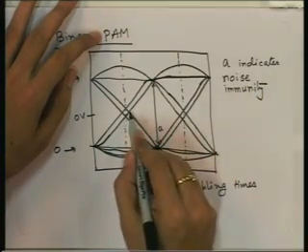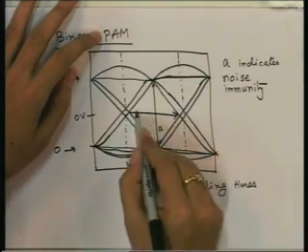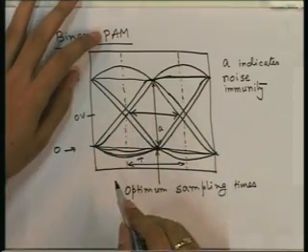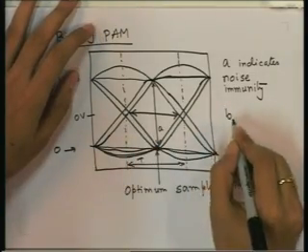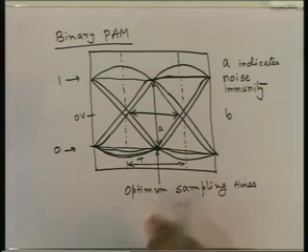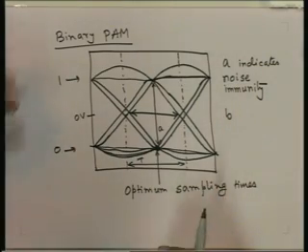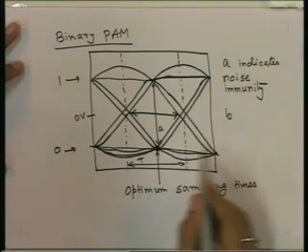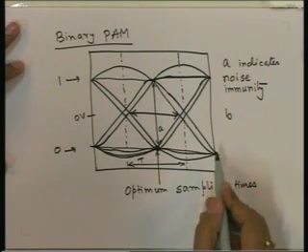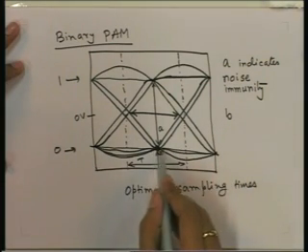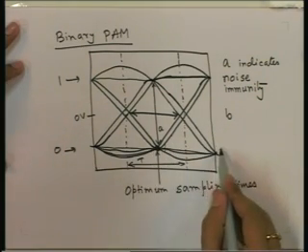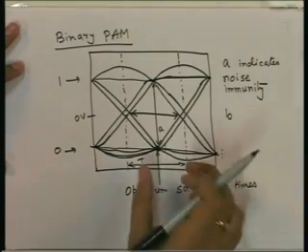Then this one, this gap indicates symbol timing error immunity. Suppose instead of sampling at these instances at the receiver, we sample here, here and then here and so on. That is, there is some offset.